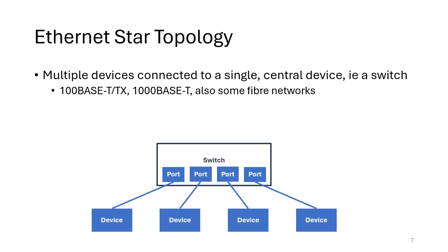Now with these networks, we can easily achieve 100 megabits, and even going up to a gigabit is very common. Today I'm seeing some devices coming out with native 2.5 gigabit communications, and it's also possible to get devices which support 10 gigabit communications, which is really a lot of bandwidth. The switch itself also needs to cope with all of that bandwidth, so depending on the quality of the switch, that may decide how much data you can actually put through.